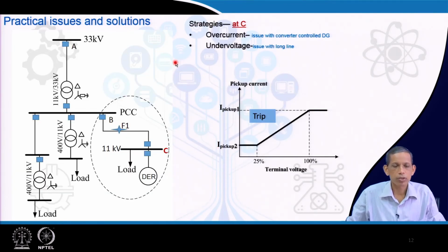Now, one other issue. These are 33 kV systems, and further downstream we have 11 kV systems, 400 volt LT systems and so on. Now, see here what the protection solution is from that perspective. One literature suggests, take a distribution system having renewable resources, DER, and then a load connected at this 11 kV system, some 5 megawatt or so, and at this bus, C bus, we are observing what the corresponding relay performance is for this breaker.